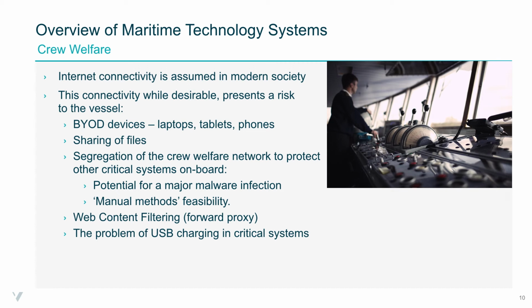What they're not realizing, though, is that when their phone is plugged in, the phone's mounted as a USB device to the underlying computer system that might be providing the integrated bridge, the ECDIS, the AIS, the autopilot, whatever it might be, and any malicious files that might be on that device that was innocently put there to charge might then infect a critical system underneath.